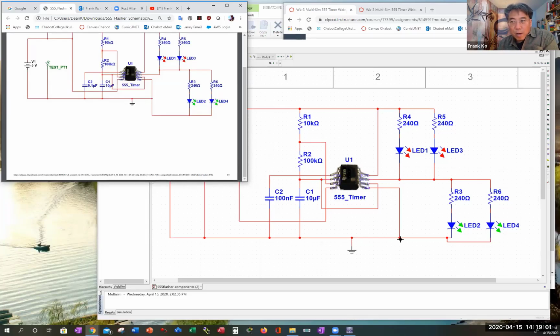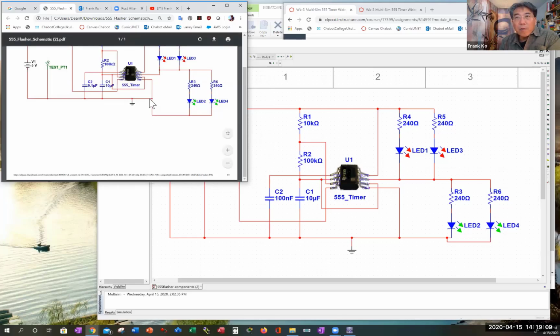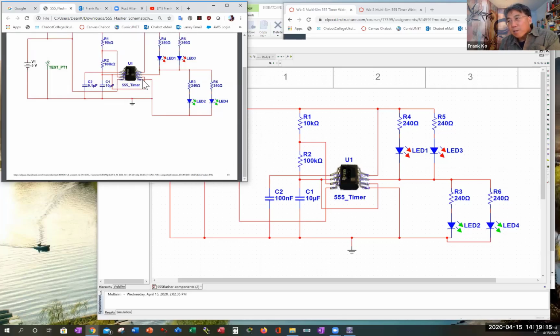There is a jumper wire from this ground wire up to pin 4 on the right-hand side. Is that evident here? Here's the wire from the ground up through pin 4 on the right-hand side. The only thing left to analyze on the right-hand side of that chip is the third pin down.